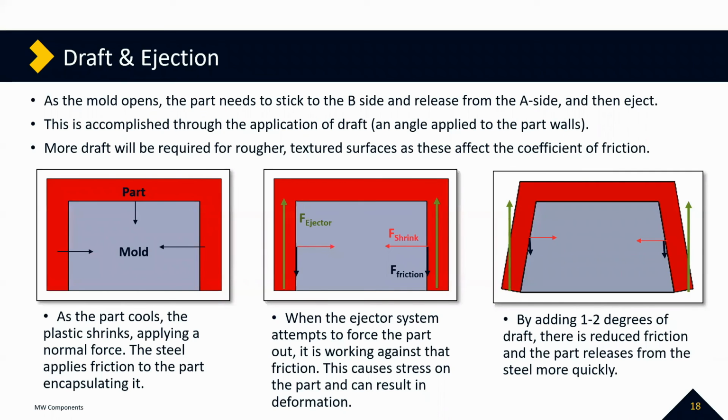And we were actually able to find, or they were able to find, a PMMA, a polymethyl methacrylate acrylic resin with a very similar refractive index. And we were then able to take that and mold it into the same shape for a tenth of the cost. And of course, significantly less weight and much higher throughputs for them. So yeah, that is something we're capable of. We've also done micro optics in the past. So we have ongoing micro optics projects as well. So it's certainly something that's viable.